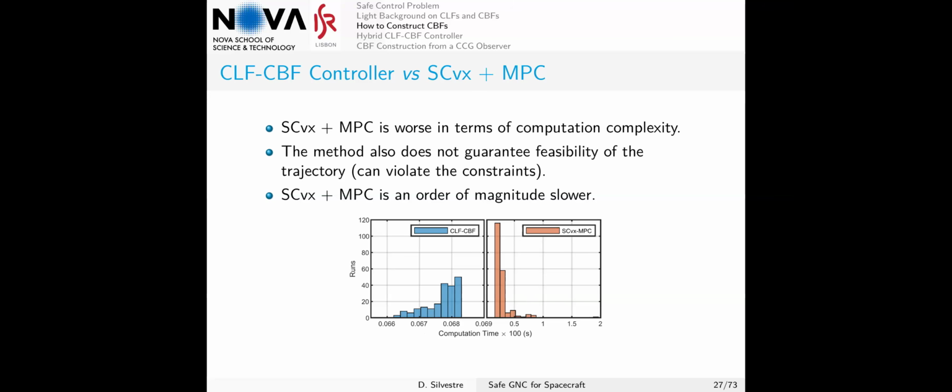But what I wanted to point out is that the computational times are an order of magnitude faster for the CBF control. Here we multiplied the computational time, because these were simulated on a laptop, and we were comparing against an application-specific processor, and that has a 2 orders of magnitude difference in terms of the rates.